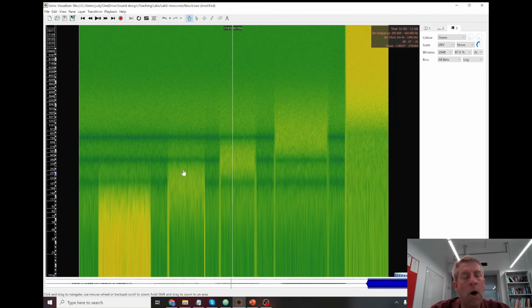One other point you notice is that the frequency content is a lot stronger for our low shelving filter at the very bottom and the high shelving filter at the top than it is for our peaking filters. And that's due to the design of the filters in the Web Audio API. So one way to create peaking filters and bandpass filters is to combine a low shelf and a high shelf, or a low pass and a high pass. And in that sense, low shelving filters, low pass filters, high shelving and high pass filters can all be lower order than the peaking and the bandpass.